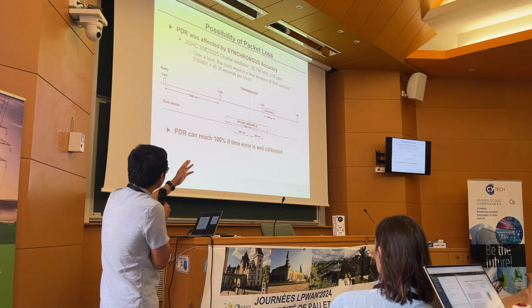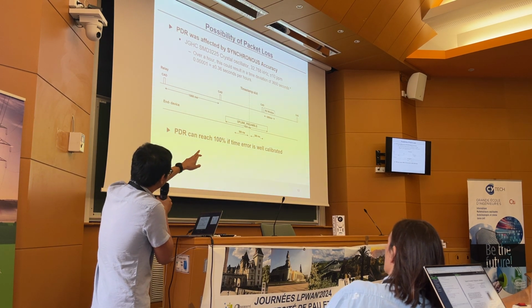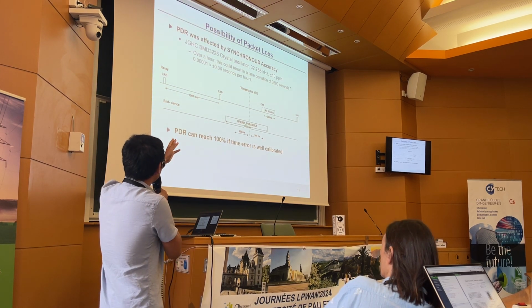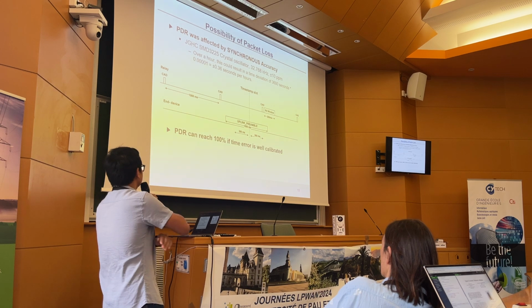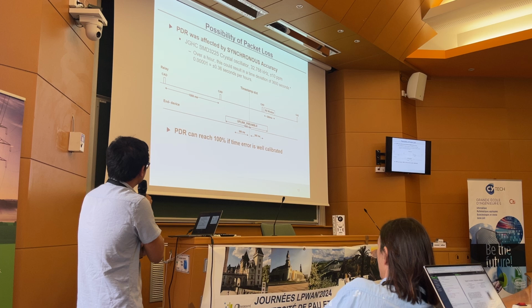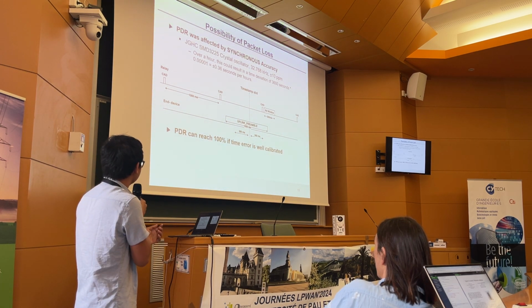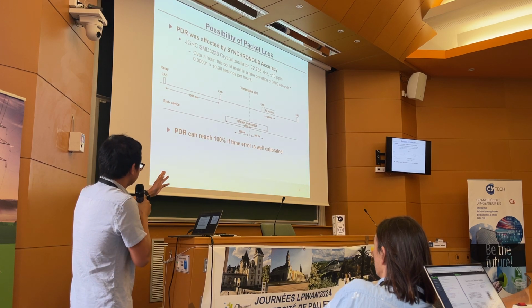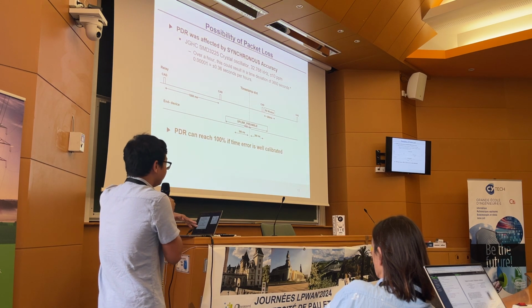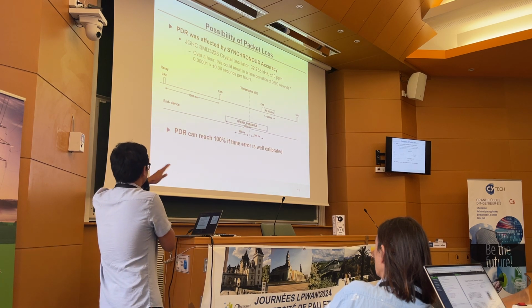For example, with an accuracy of plus or minus 10 ppm, it means that the time error is around plus or minus 0.26 seconds per hour.